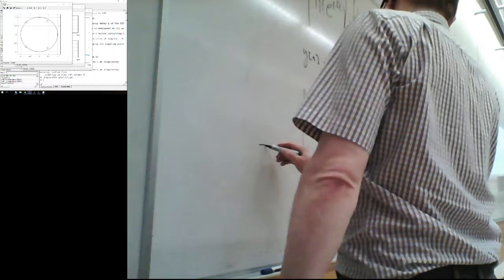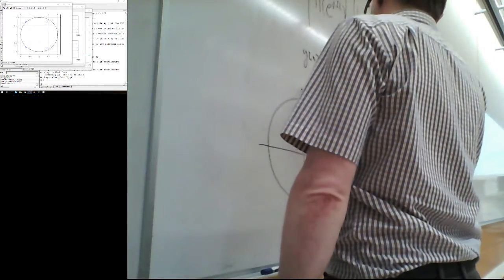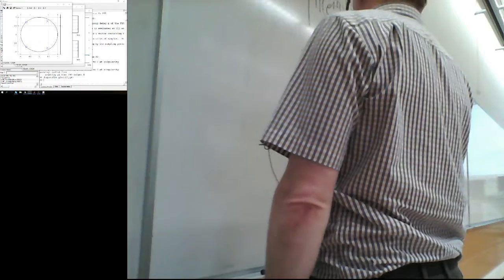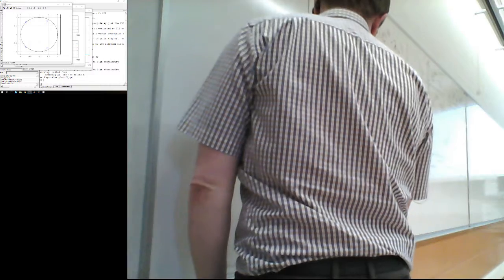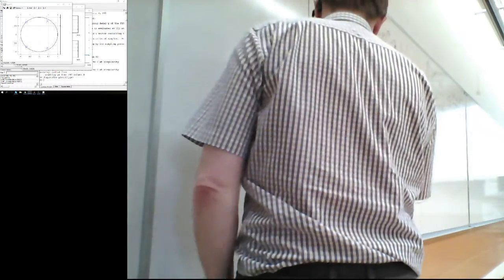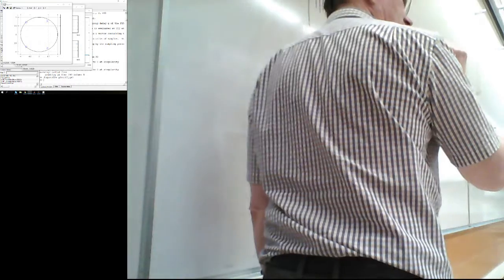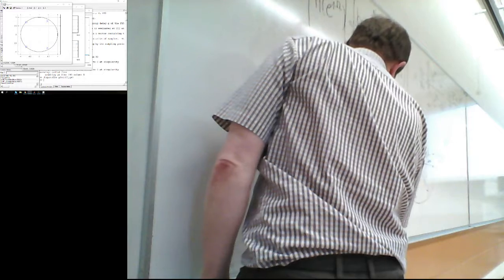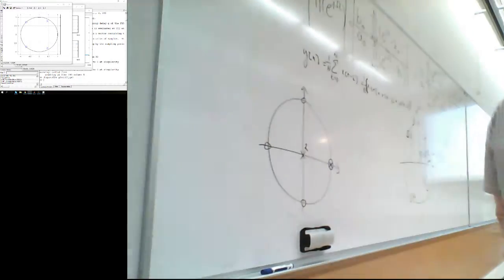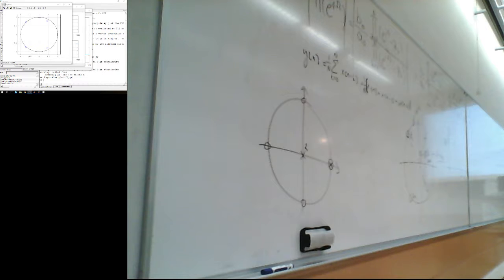And the Argand diagram would look like something like this. Actually, for 4-point running average, it looks like that. Okay, and the poles are all here. How to make the same system so it's recursive, but still FIR. You take one of those poles right here and also the corresponding, and you cancel it by 0. What did I do here?